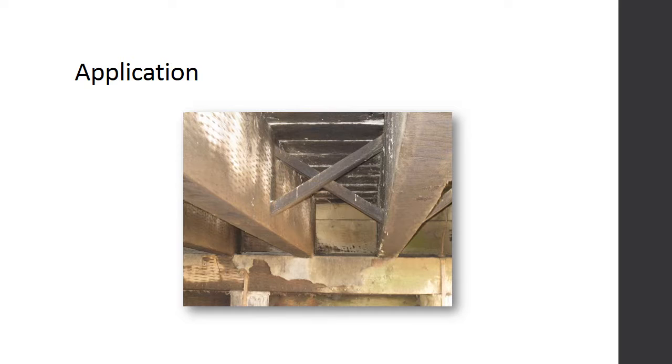These repair methods are used for strengthening timber stringers or girders, like those shown, that have localized minor to moderate deterioration that has weakened the overall strength of the member at the ends or along the span, by attaching steel or timber members to timber stringers or girders using through bolts or lag bolts.